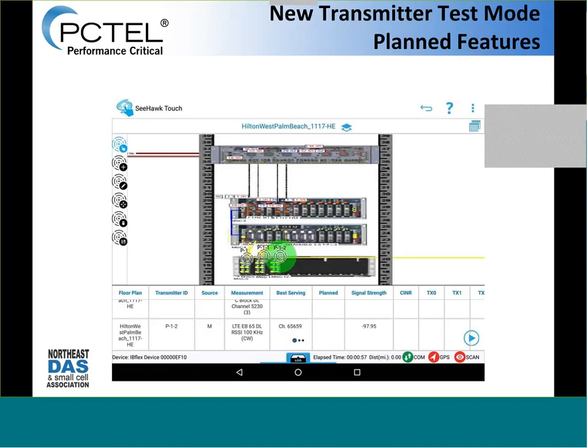We've also found that this is very useful in the head end. Oftentimes, you're going up to a patch panel with a series of ports on it, and you want to make the same measurements on the patch panel that you're making out at the antenna. So the same list of channels and cell IDs. You take a picture, photograph, drawing, whatever you have of your head-end equipment, and create an icon for each of the ports you're going to test. Now you can do the same simple execution where you tap on an icon, run it, and once you're done, it creates the same kind of table below.